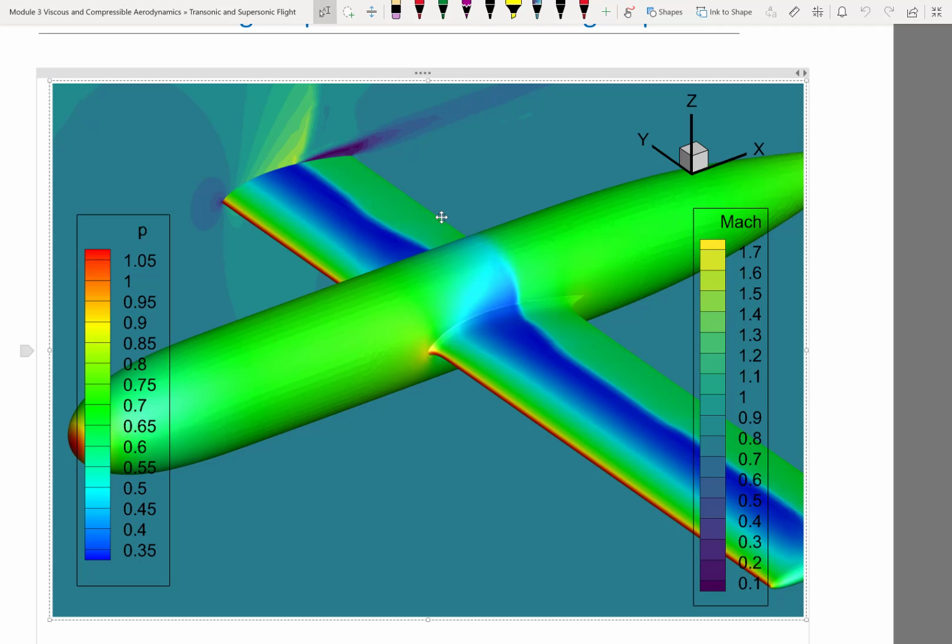Adverse pressure gradient, exactly. So over the shock wave, what's happening is that we do have conservation of momentum, right? The flow suddenly decelerates from supersonic speed back to subsonic speed. That means the pressure has to what? Increase suddenly over a very short spatial distance, right?